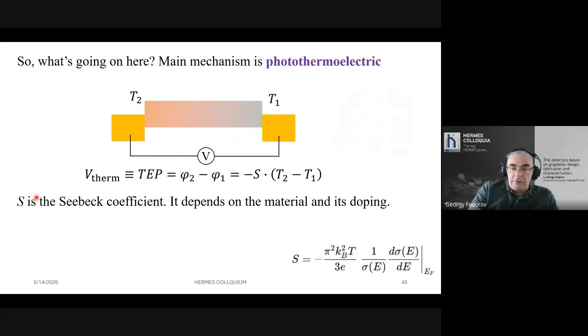And what happens here is that when you feed electric current in this system, you heat this channel. In this case, it's graphene. And you can do it in two different ways. What I show here is that due to a certain asymmetry of the channel, one side is heated more than the other. Again, what I'm talking about is Joule heating of the channel induced by the terahertz frequency current that is driven here by this radiation to which the graphene channel is coupled.